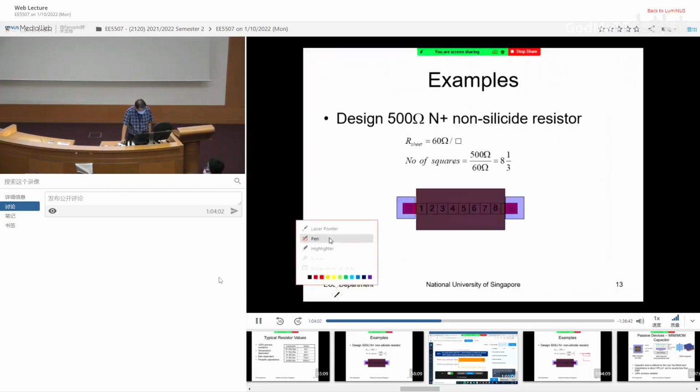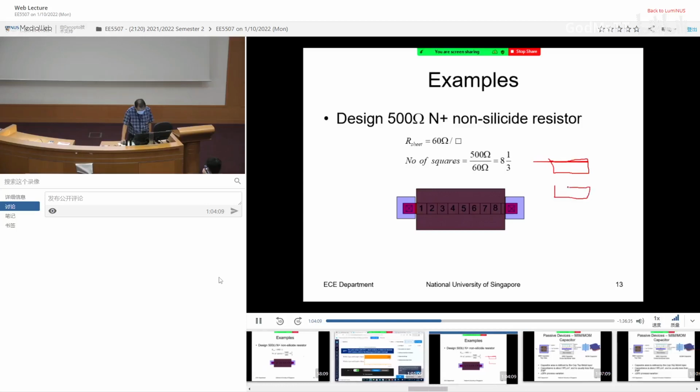that's why I don't have a pen to draw. Now consider a square. So you have two of the same shape. You draw it, but when you fabricate the devices, you don't get a nice rectangle. What you get is, sorry, I should use a different color. So there will be these checkered things at the edge. Same thing here, same thing here, same thing here. This edge variation is the one that is causing the mismatch. You cannot guarantee the edge of one side is exactly the same as the other side.